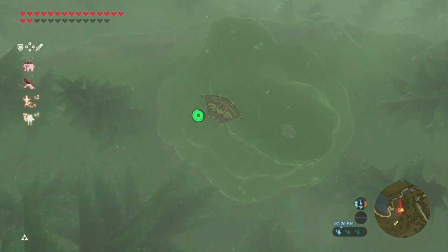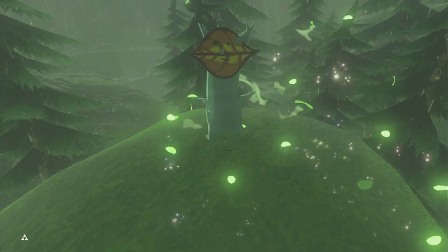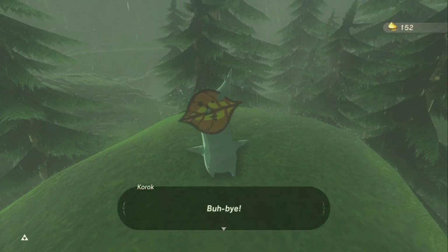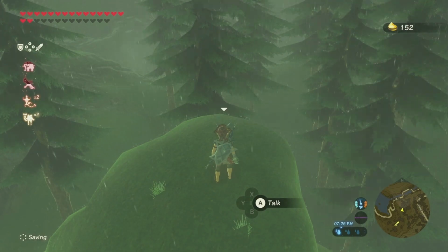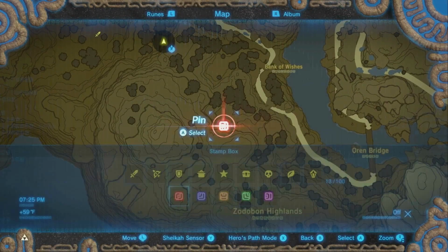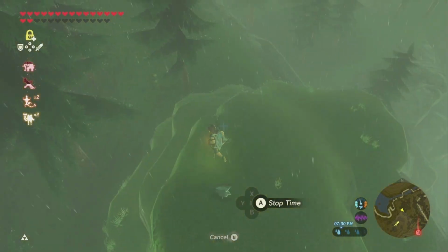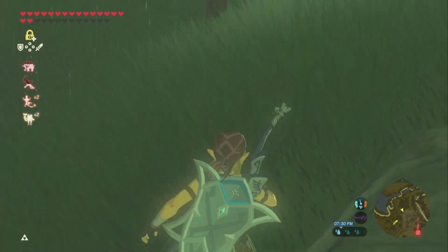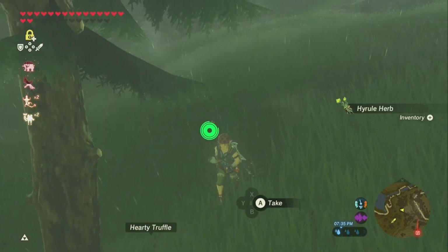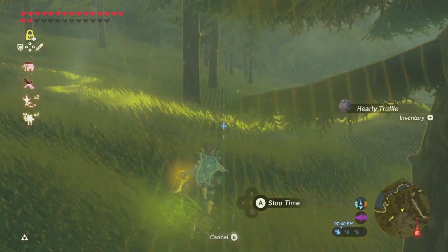Dual water heaters. Domestic water heaters are typically limited to 75 or 80 gallons as a practical matter because of their weight and the need to get them through doors. Some large houses require more hot water than this. There are two common strategies for accomplishing this. Two water heating zones: two separate water heaters can be installed in different parts of the house to serve different plumbing fixtures. The house is essentially zoned from a hot water plumbing standpoint.